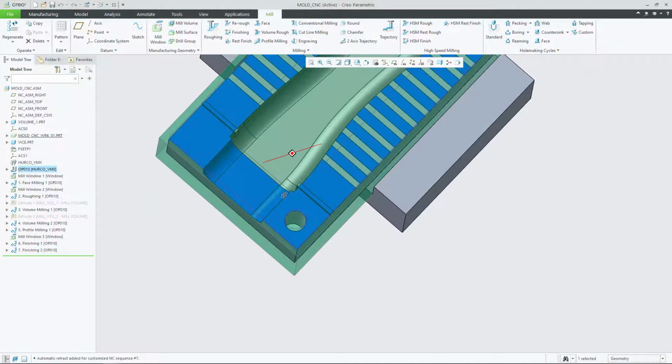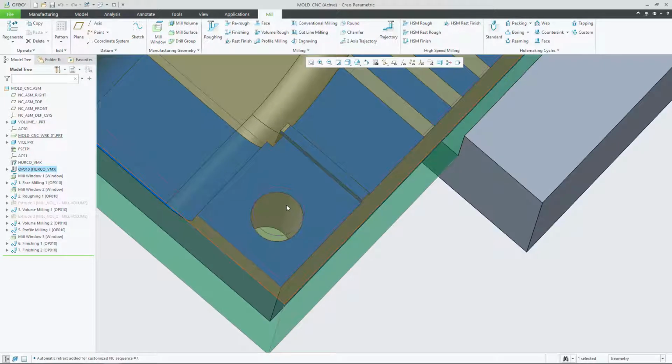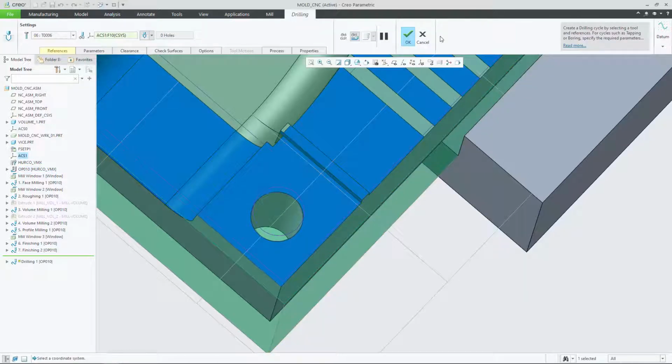sequence type, which is a drilling sequence, which is quite a simple sequence type. The tool doesn't really cut any material. Obviously when you're drilling, it doesn't even really cut any material in X and Y as such. The drilling sequences merely move to their drilling location and then drop in Z down into the part, and obviously drill the geometry. So let's say that we're going to create a standard drilling sequence.